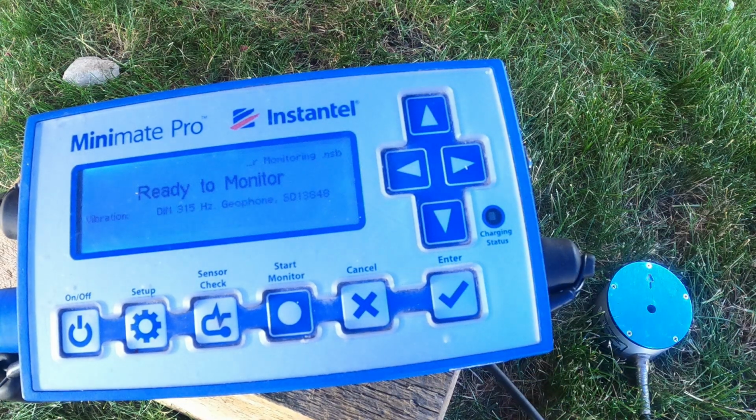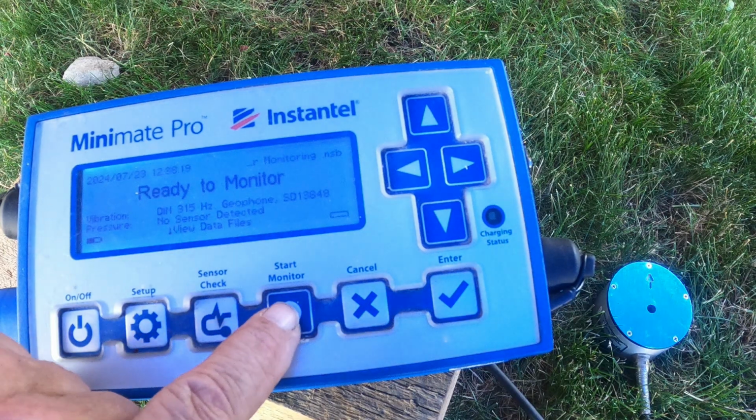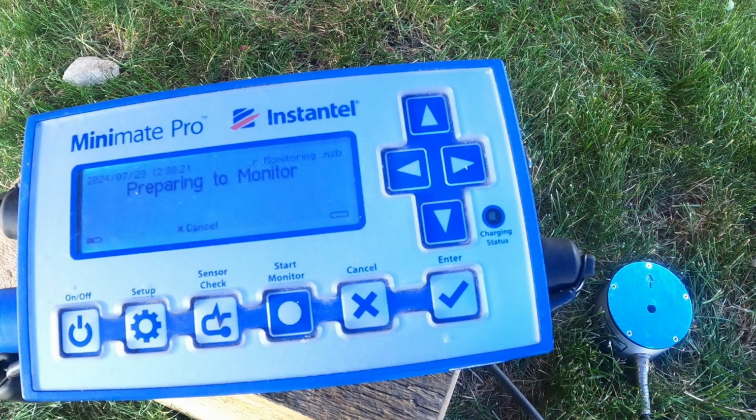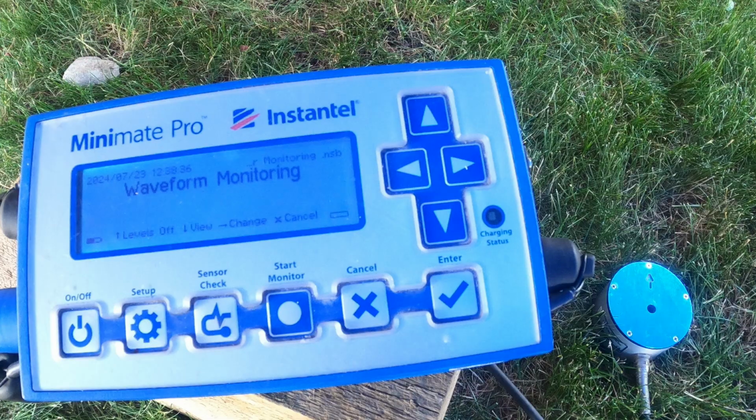So now if I was expecting a lot of acceleration in and around this sensor because I was very close to the source, I would probably sandbag the sensor, and then I would redo a sensor check. But let's go into start monitoring. So for geophysical operations, I have selected sensor check before event. So it's going to go through the sensor check process here, and then it's ready to monitor.